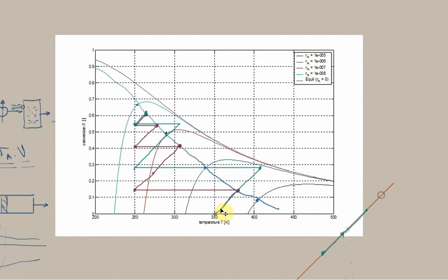So you see here, we've taken 10 degrees short. So we don't have a small reactor anymore, but we've got a higher conversion. And we cool back, and then again, we use the 10-degree criterion. And then we cool back, and you see we reach a slightly higher conversion. And in fact, we could go a bit further and stop this only on 10 degrees and be consistent with our algorithm.